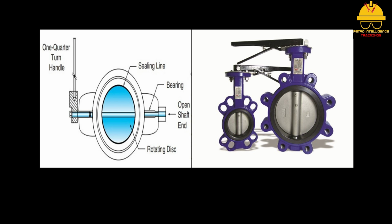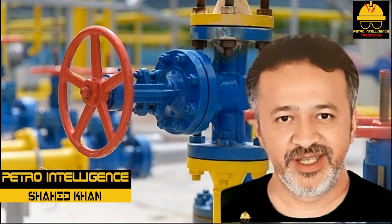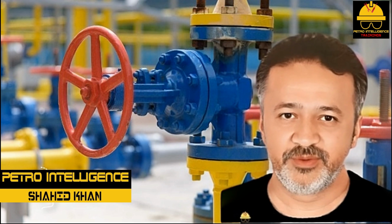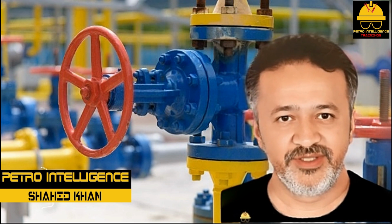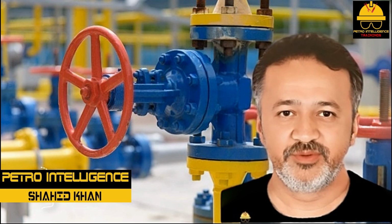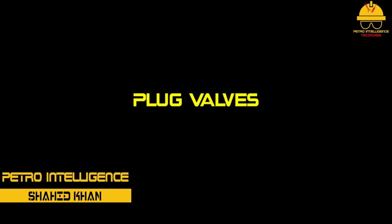Butterfly valves are used for throttling, however, it should be noted that they have non-uniform flow characteristics. 50% open may provide near maximum flow. Butterfly valves are designed to be operated at low temperature and low pressure. They are commonly found in cooling water and heat exchanger systems throughout the process industry. The seats in a butterfly valve can be made of natural gum rubber or suitable plastics.